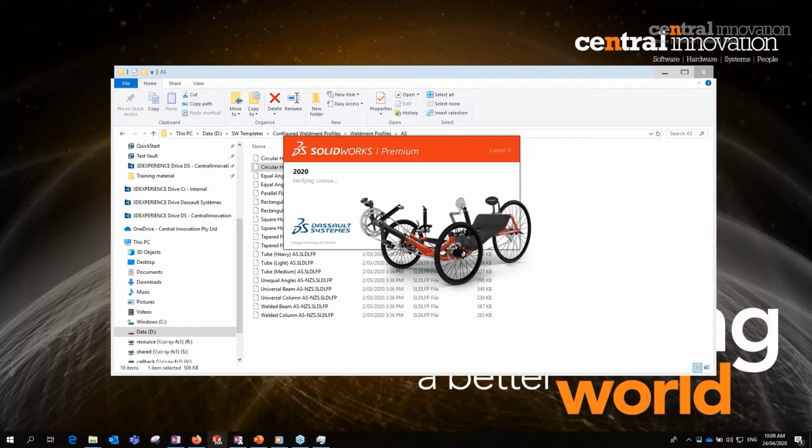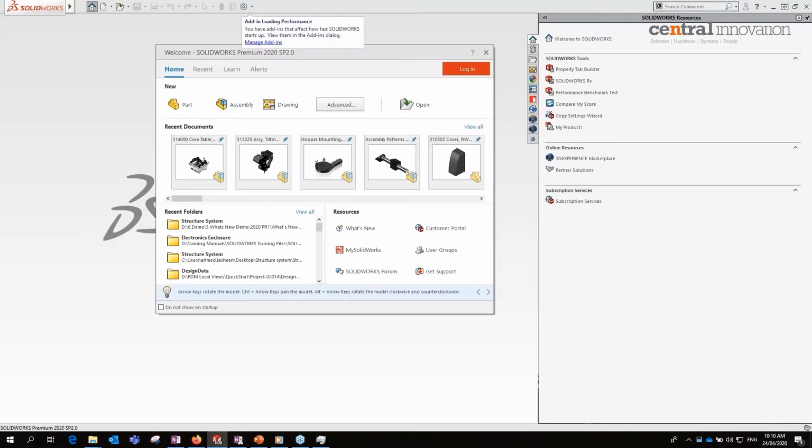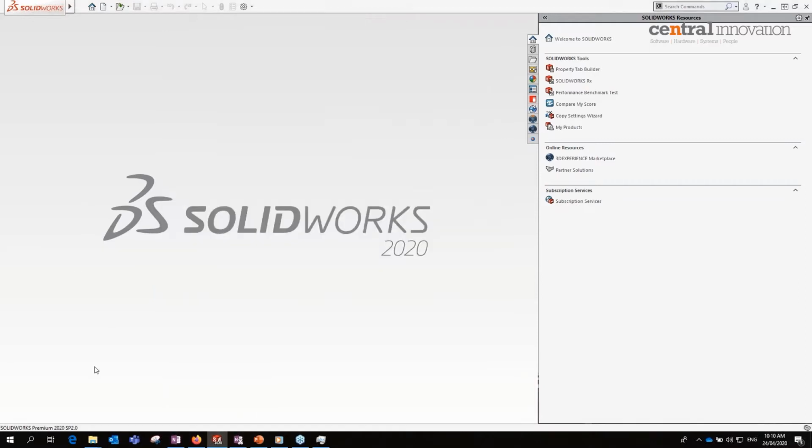So as you know, in Weldment, when you build several members, the concept is you have to select a group of members in parallel or series. And if you have to modify a particular member, part of a group, after you create it, you have to edit the structure member feature, exclude this member from the group, then create a new Weldment feature for this particular member. So modification for the Weldment feature was a little bit of a pain, and even the creation, because of the rule of a series selection or a parallel selection for members. So now I will show you.